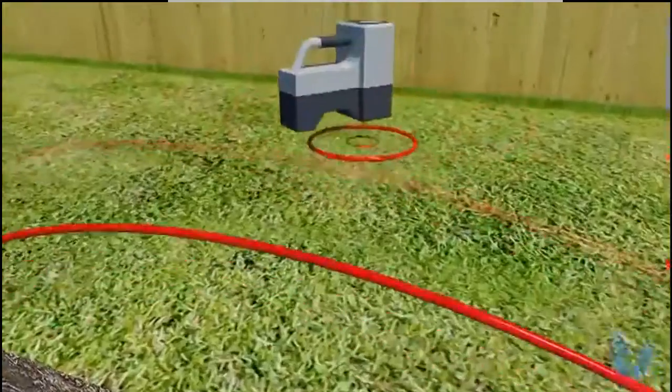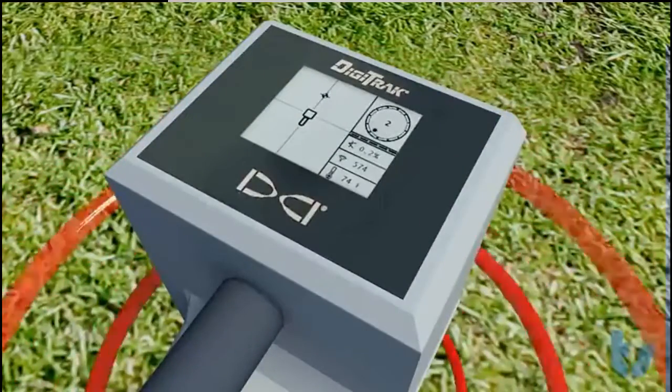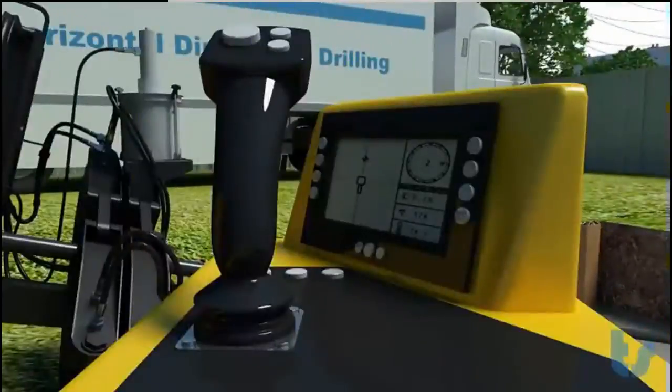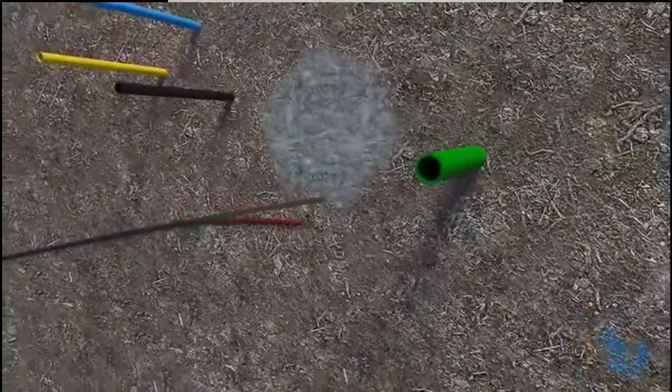So you can see him drilling through here right now. He's drilling, I'm assuming it's he, probably being sexist, but most drillers are still males. He's drilling down, and you see the signals going to the surface. It is telling him the depth, the rotation, and the inclination of the pipe. They can read that as a walkover. They can also read it back at the machine.